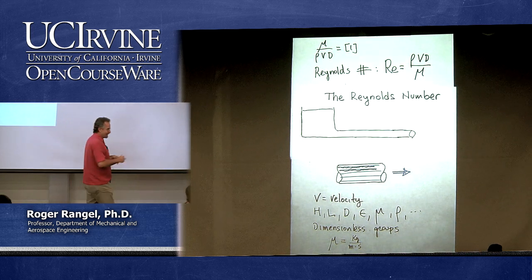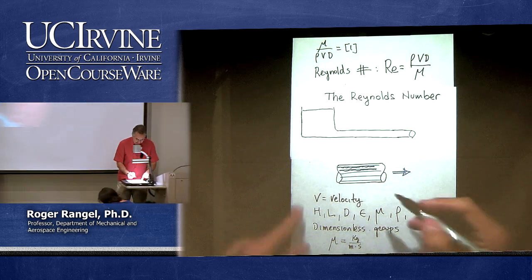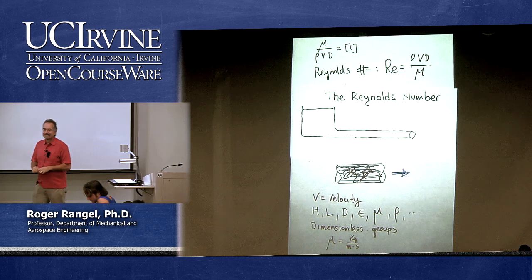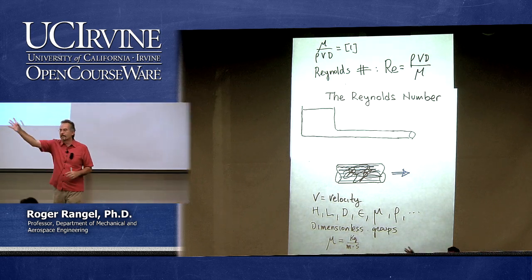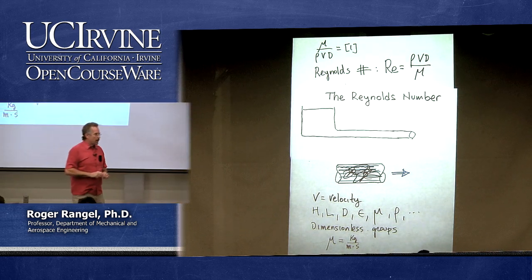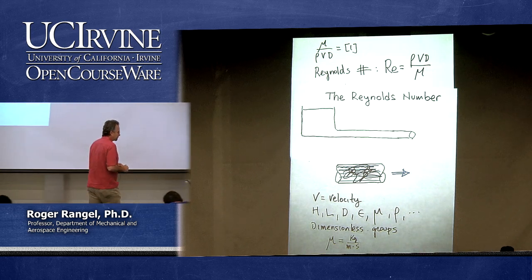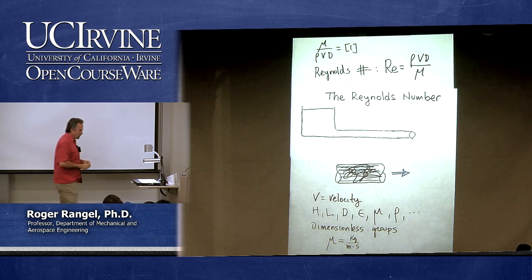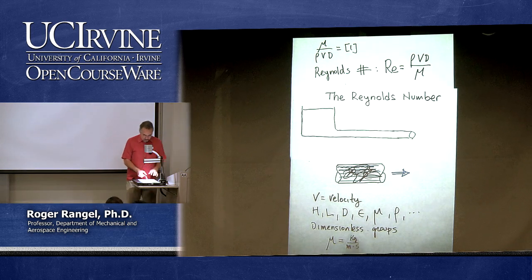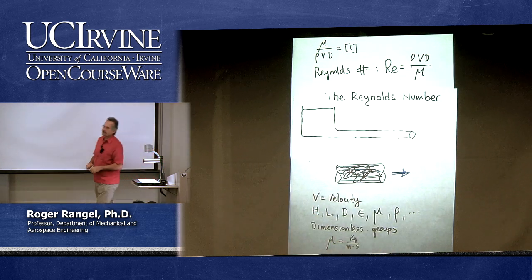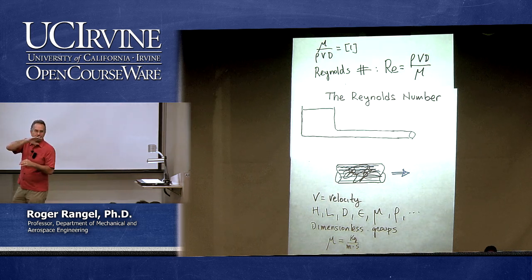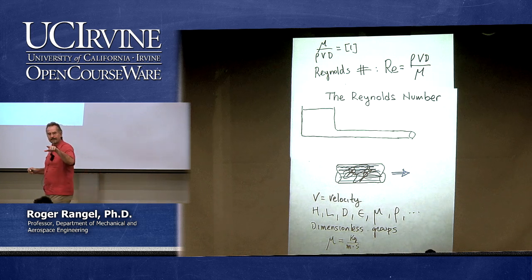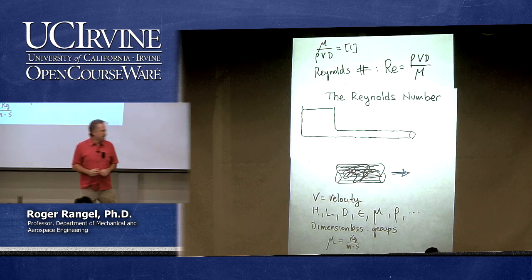Wild, right? A mess, right? They might look like that as the flow goes, because the flow now is fully turbulent. So in fact, the Reynolds number controls that transition. We are calling this messy flow turbulent flow. What do we call the other one where the lines are nice and smooth and horizontal? Laminar flow, right?